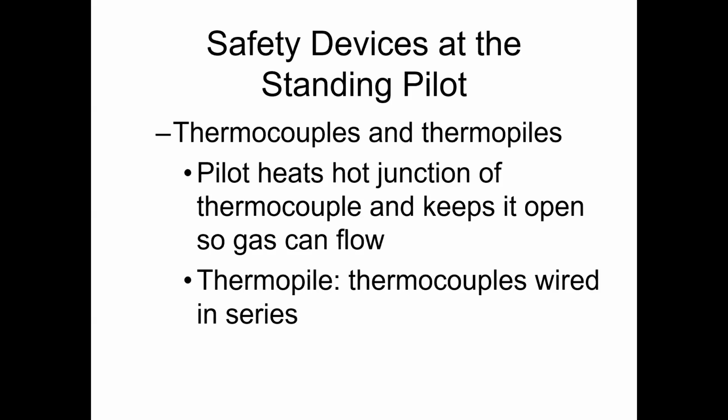So for a standing pilot, this thermocouple sits in front of that flame all the time, because when is that standing pilot burning? It's a standing pilot, right? It's going to be burning non-stop. It's going to be operating as long as that system is powered on, even in standby mode. The only time the pilot goes out is if it blows out, or something like that happens. Now, with the thermocouple, it's going to be sitting right in the front of that flame.